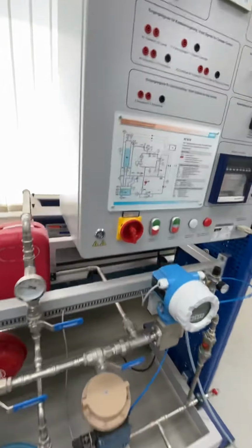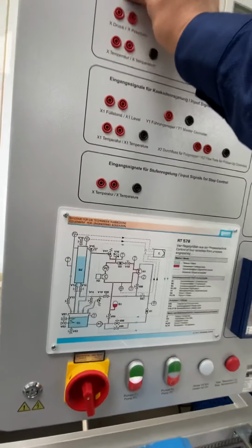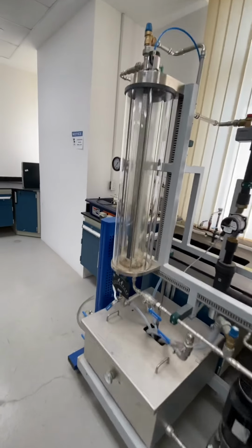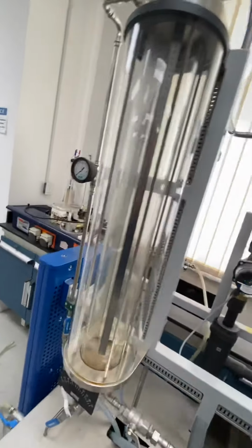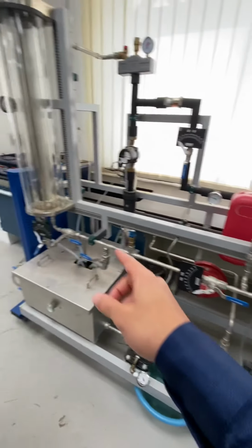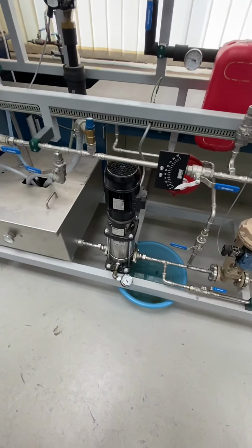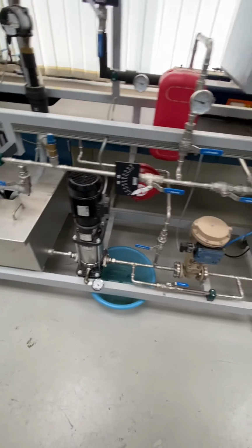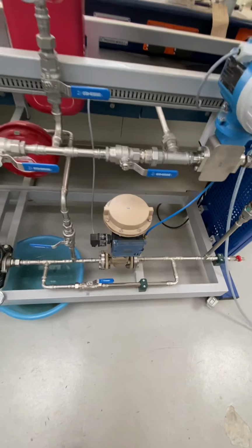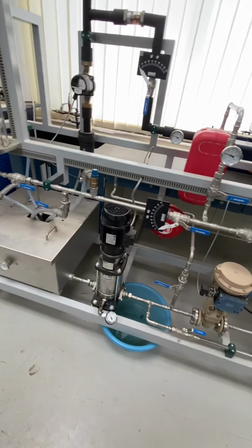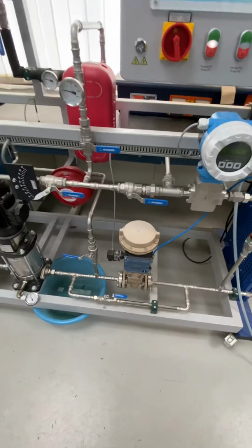So with this experimental setup right now, with the level control, the objective of the experiment is to control liquid level inside this tank B2 at different set points by manipulating water inlet flow rate to the tank using the variable speed pump as an actuator. So for now, let's just imagine, gentlemen, that there is no automatic control valve, because with the variable speed pump you don't need an automatic control valve.